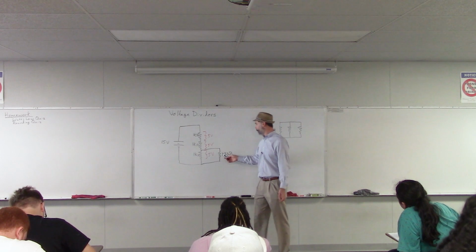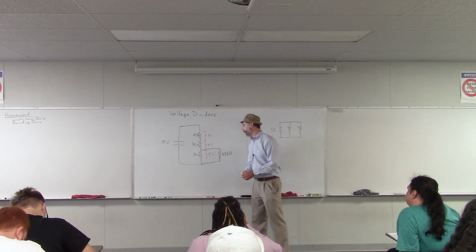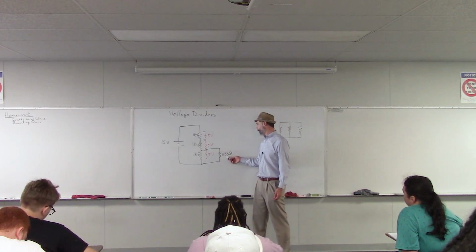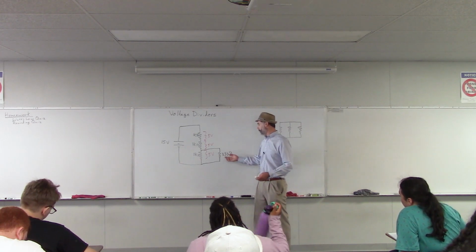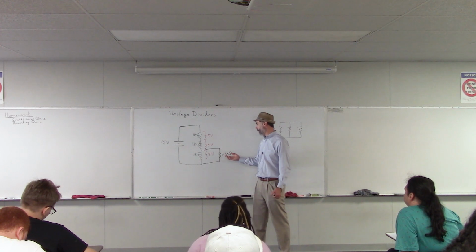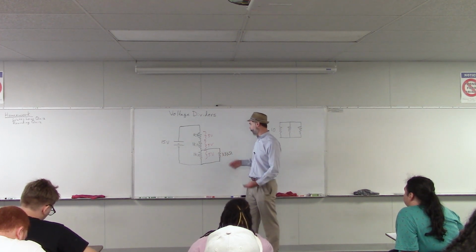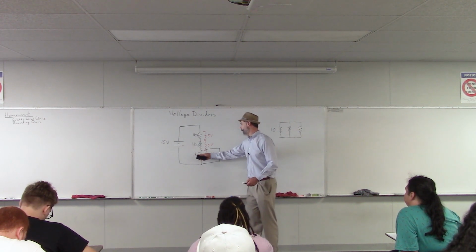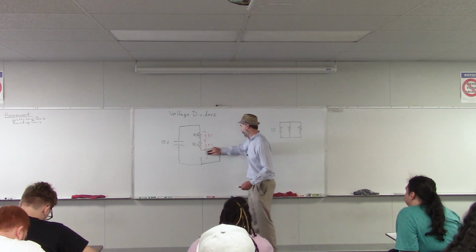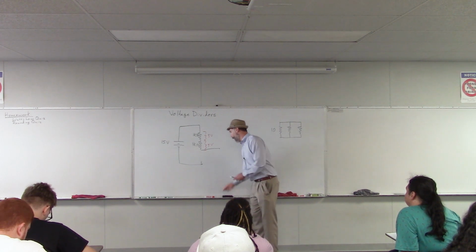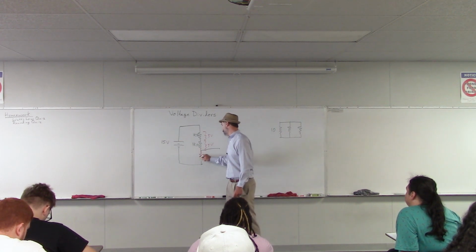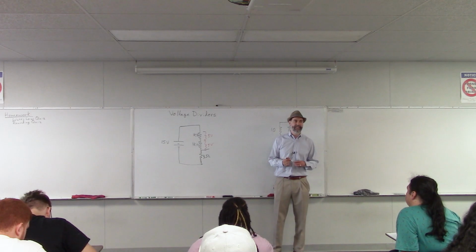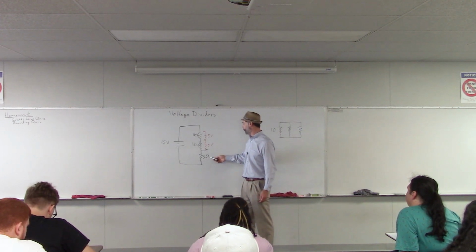So now you've got this 3.33 in parallel with a 1 kilo ohm resistor. And we know that the equivalent resistance is going to be less than the smallest one, so it's going to be a little bit less than 3.33. We could do the math, but for the sake of argument, let's just call it about 3 ohms. So really, what you've done is you've taken this resistor out and replaced it with essentially a 3 ohm resistor. Okay? So now, are you still going to have 5 volts, 5 volts, and 5 volts?